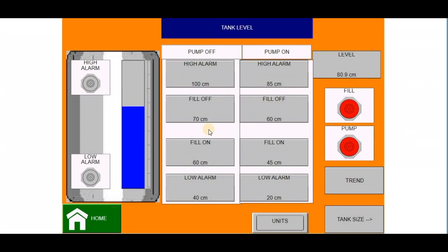Also, as a precaution, after the pump has de-energized, the system will wait for a predetermined amount of time to allow the water to flow back into the tank before any action will be taken on the part of the control panel, so as to avoid any overflow. And all of this activity is tracked in a trend in order to monitor the operations history of the system.